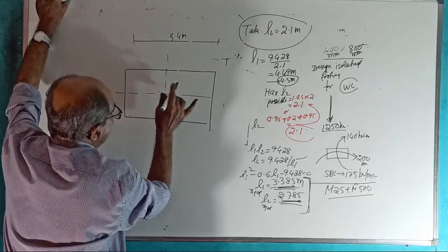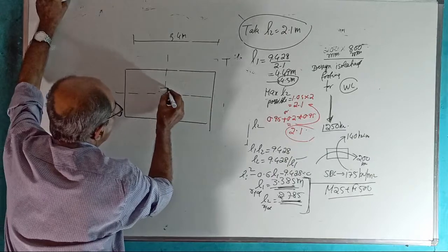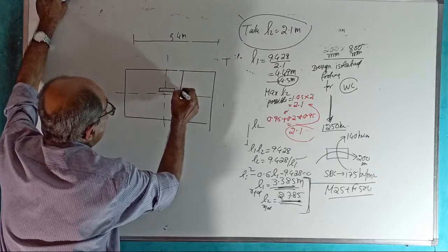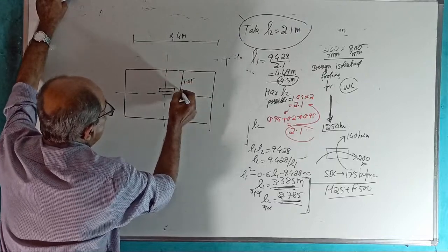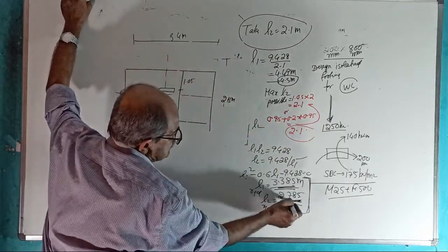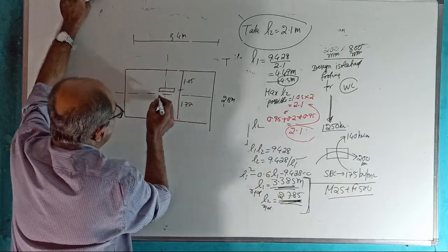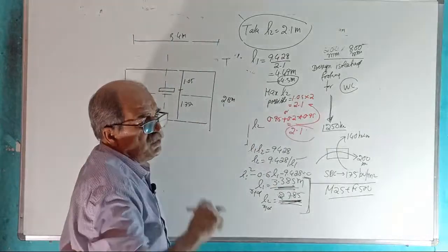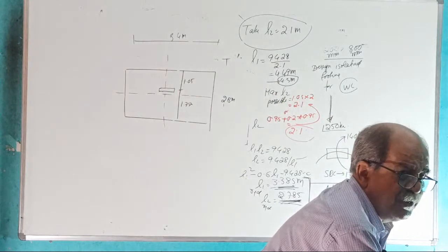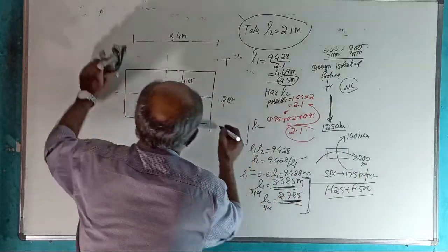No, not that way. Your footing will become, central line is here. It will become this way, correct? It will become this way. This is 1.05 meter. This will become from 2, suppose you give 2.8 meter. Why? 2.785, 2.8. This will become 1.75 meter. Clear? This will be what footing? Tell me. This is called what footing? If you don't maintain, if you don't give equal, either side same, this is called what footing? This is called eccentric footing.